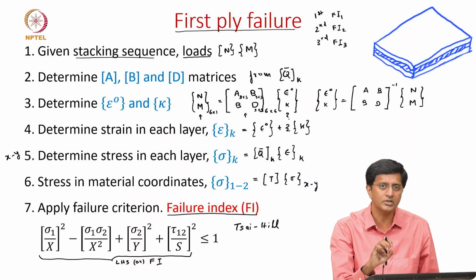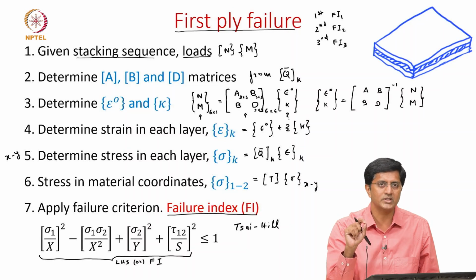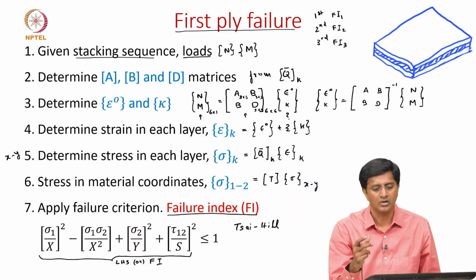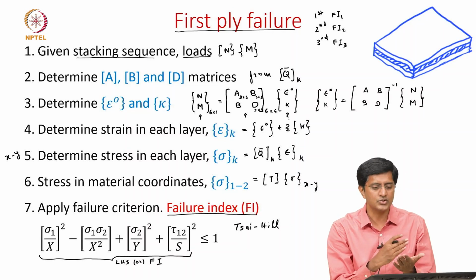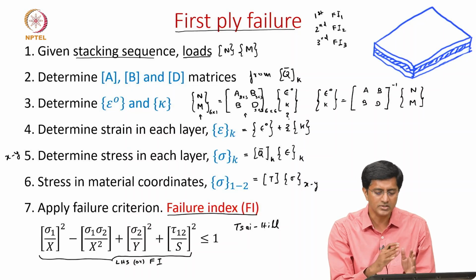But how do we know all this information? We just need to put these failure index values in ascending order. Once you put them in ascending order, the one which has the highest value indicates the one which fails first. Or let's say if your question is only to find which of them fails first, this procedure is good enough.